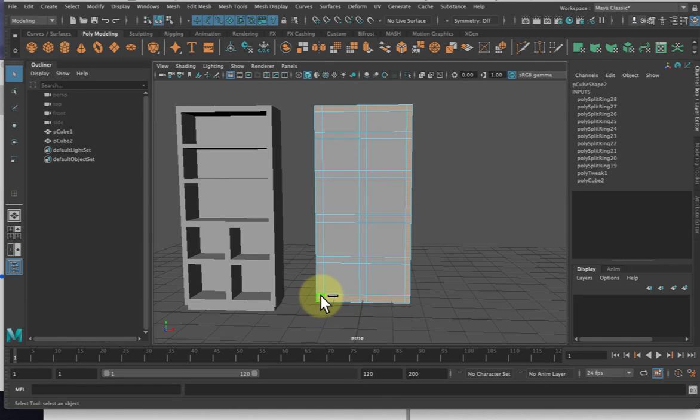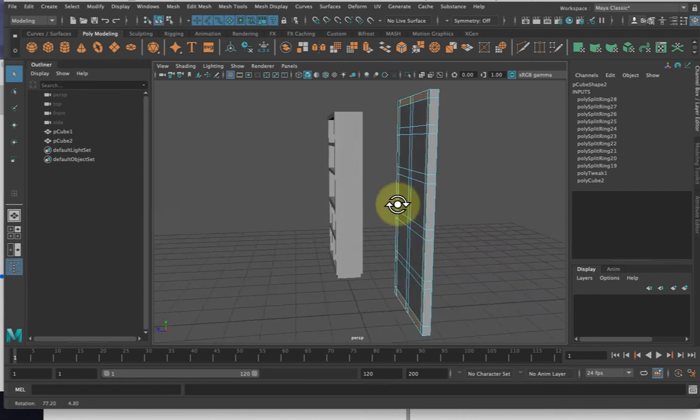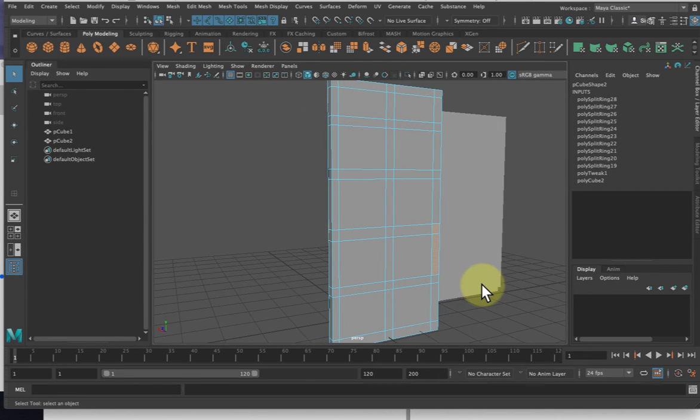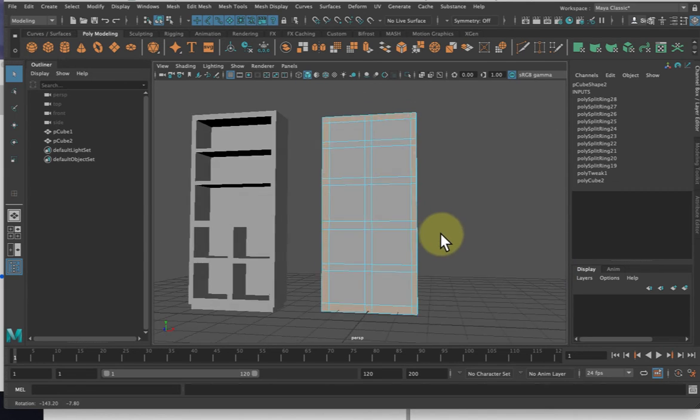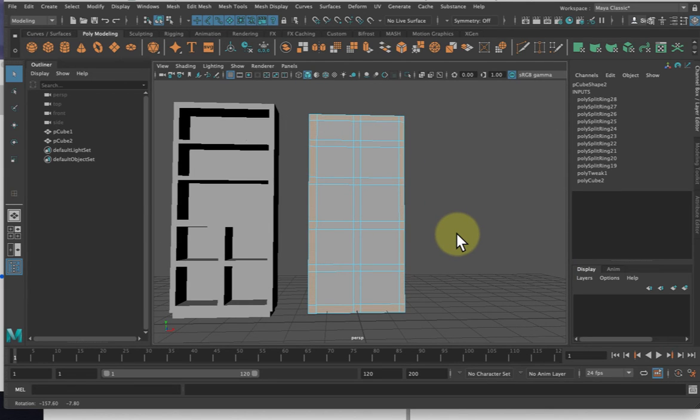Now I am going to do this all at one time to avoid faces being on top of faces when I go to extrude this. So you can see I've selected all of those on the edges. Again, I'm going to go on the back side and make sure I haven't accidentally selected additional faces, like you can see I just did there. So it looks like I'm clean on all different sides and edges. Now again, I don't want to extrude out because then I'm going to have faces touching each other on the inside here. So I'm going to continue selecting these faces going across.